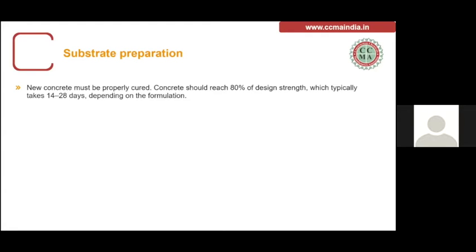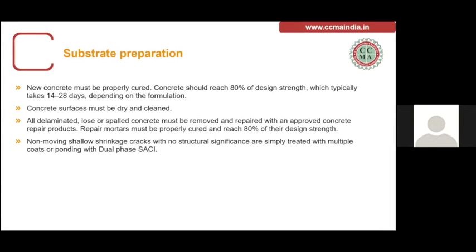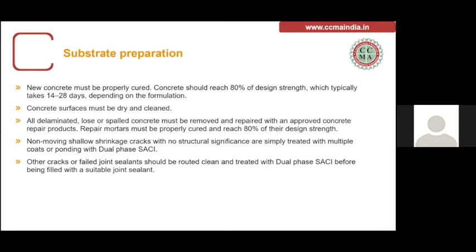The application part is, as you can imagine, quite simple. Concrete has to be properly cured, and it should have at least 80% of its design strength. It should be applied on a dry surface, because we want the material, the silane, to penetrate inside, and it should not be diluted with water. All the loose and spoiled concrete, in case of an existing structure, needs to be taken care of and repaired properly. And if there are any cracks, then we suggest you can pond it, or you can fill the crack even with this liquid. So it's an added benefit.